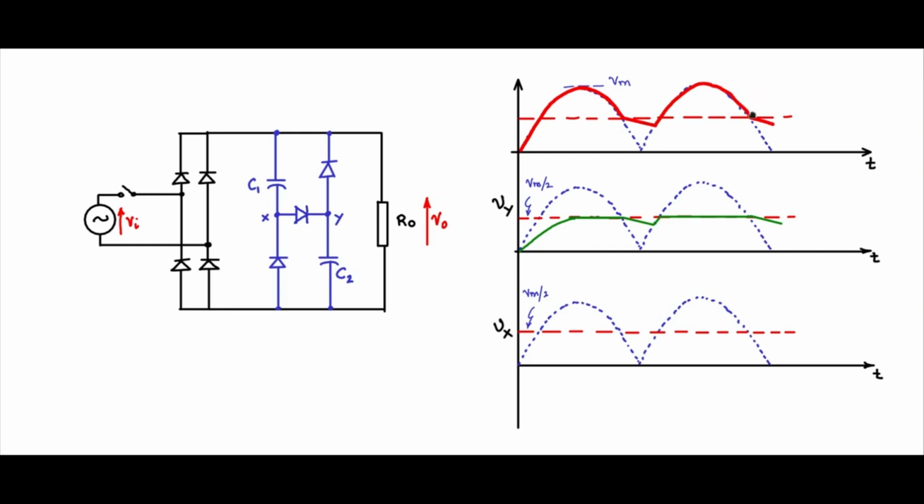Look at the very large ripple, but look at the conduction time. The conduction time is all this time, the current conduction time. So this is V0. So let me draw these critical marker points like that. During this time only the current is 0 here. This current I is 0 here because at that time the capacitor is discharging, and during this time you will have the current.